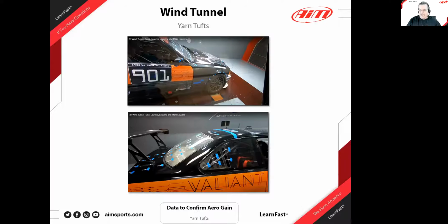And that's exactly the thought process, David, we're going to chat about: looking at some of that data, not necessarily John Block's exact formulas, but at least looking at that data. So AJ is doing that, and if anybody's interested, contact me later. There are a ton of different suspension sensors available, but one of the ones that are fairly inexpensive is the General Motors ride height sensor that a lot of people like to use. I've seen them as low as $35-$40, maybe averaging $75-$80 for a brand new replacement sensor that has good resolution, and you can get pretty darn good suspension travel data with it. That makes this an analog sensor that's in the range of what a lot of people might be able to do and want to do.